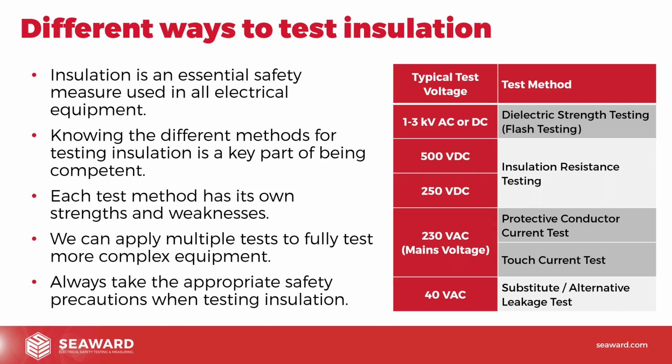And a few years ago, going back to maybe the second edition of the Code of Practice, flash testing, dielectric strength testing, was mentioned as part of PAT testing. There are still some companies, particularly tool hire companies, who still carry out flash testing as part of PAT testing because they believe it's worth doing. They've got equipment that's quite resilient, but it's going to be used in harsh environments. It's high risk equipment, so they would still carry out dielectric strength testing.